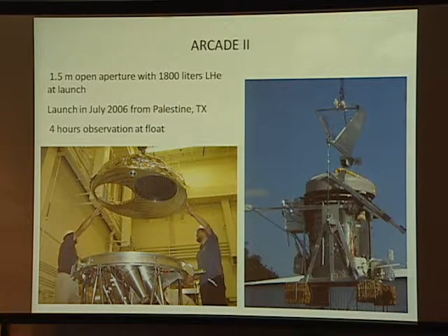Through a process of experimentation, we discovered that one of the best ways to do that was to have some of the gas go up through this lid here, which has a number of radiation shields, and so it cools those shields as it winds up. And then it goes out the top. You can see this little yellow and black snake here. That's a little piece of dryer ducting that carries some of that gas away.